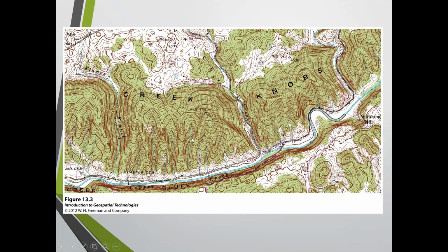But our contours here, you have 2 kinds of contours primarily. I'm sure you guys are familiar with that. As you look at those contour lines, some of them are darker brown and some of them are lighter brown. The darker browns are usually called your major contours. The lighter browns are your minor contours. And if they have numbers inserted in them, such as 1800 or 1900, that's what's called an index contour.